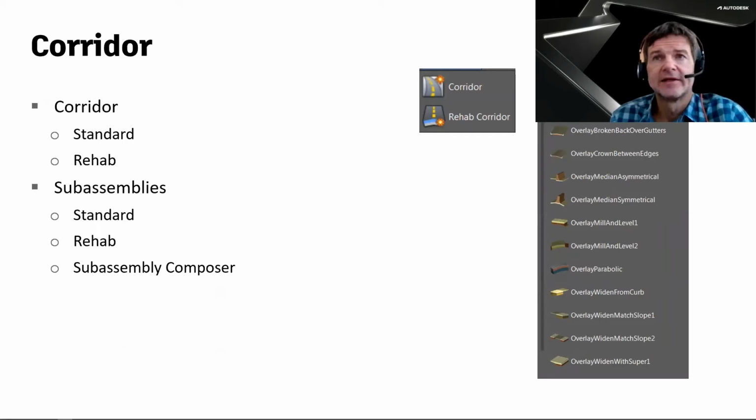resurfacing, and intentionally I don't do anything with the profile, because the profile will be a result of the resurfacing. So basically I'll build a corridor based on the alignment, on the existing conditions, the existing road, and based on criteria, the system will create the profile.